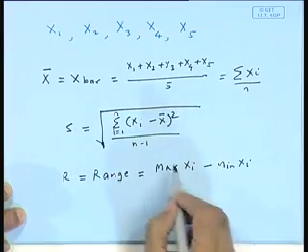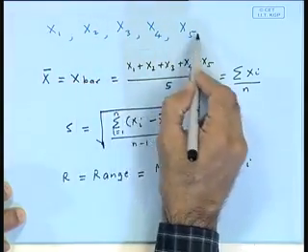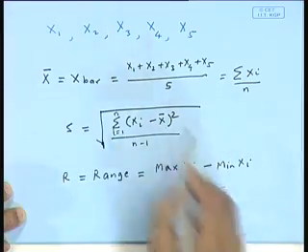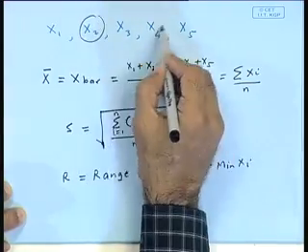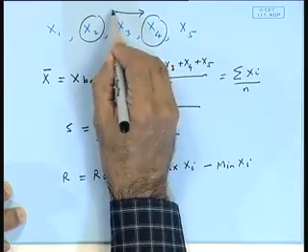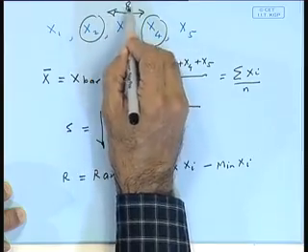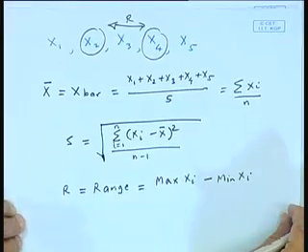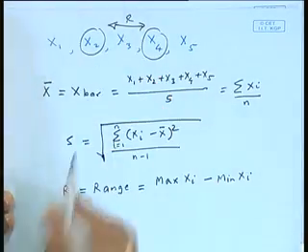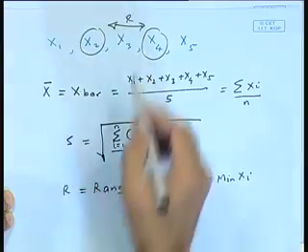The largest value in the collection of the data there and the smallest value in the collection of the data there. So the difference between the largest quantity and the smallest quantity, this difference here is R. This is the range. And that is something that we'd like to get an idea of, because range indicates, again, like standard deviation, it indicates precision of the process.